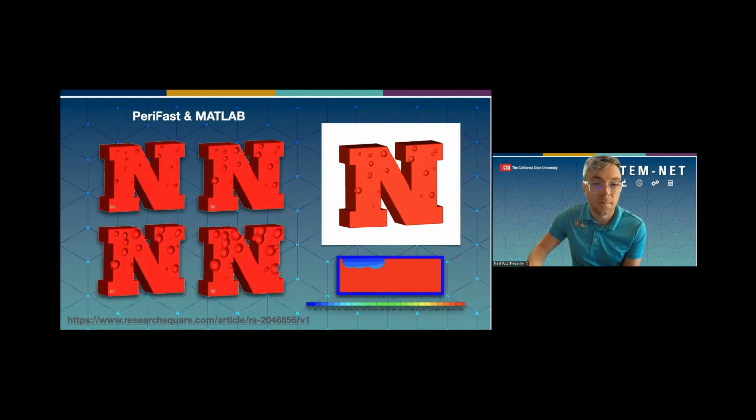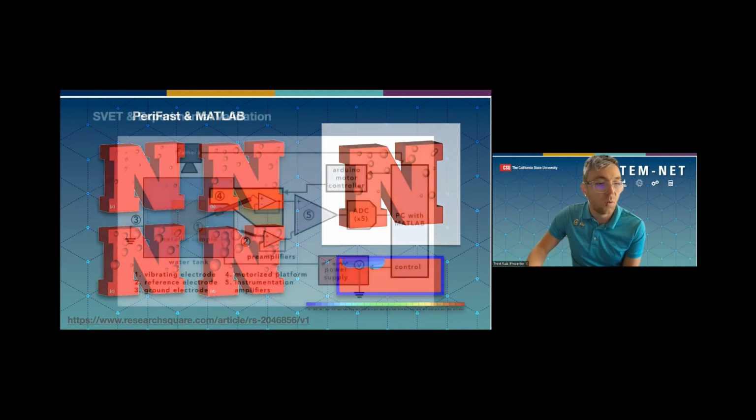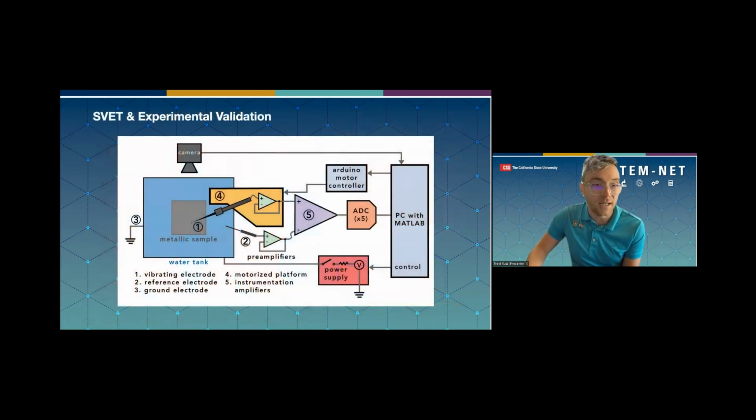To verify these computer models of corrosion, we're going to be implementing a SVET experiment, and this measures current densities above a corroding surface. Industry standard machines use costly piezo electrodes to basically vibrate the electrode. The apparatus on the screen here substitutes the piezo with a solenoid, and to keep the solution space wide enough, an electromagnetic tactile transducer will also be explored. The solenoid and transducer techniques will be compared to industry standard current density maps.